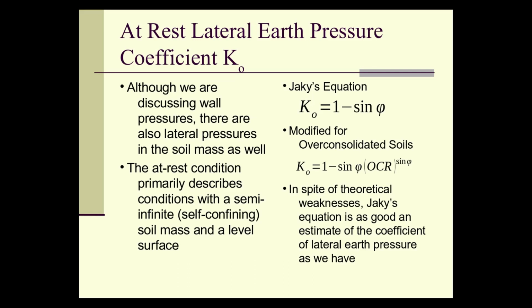The only modification you commonly see for Jaky's equation is the modification for over-consolidated soils, where they add this term at the end: sine phi times the over-consolidation ratio, or the pre-consolidation ratio, to the sine phi exponent. And we talked about that in consolidation settlement.